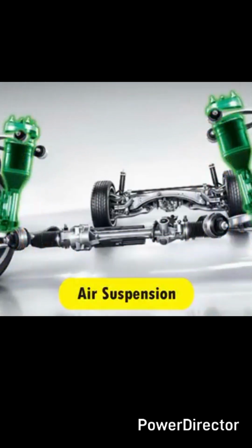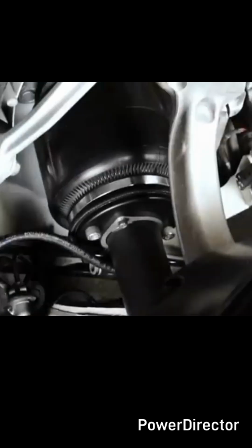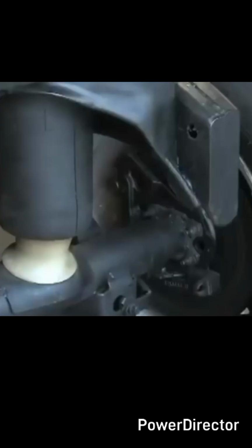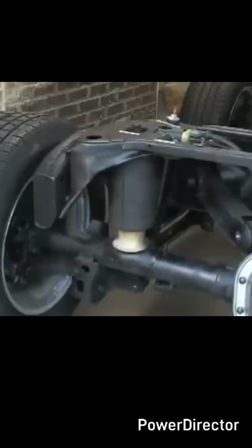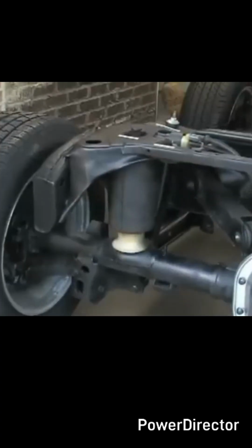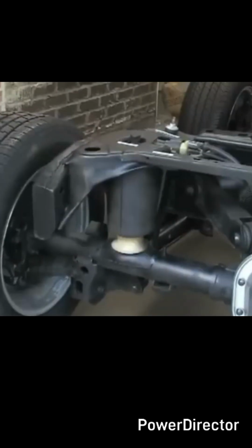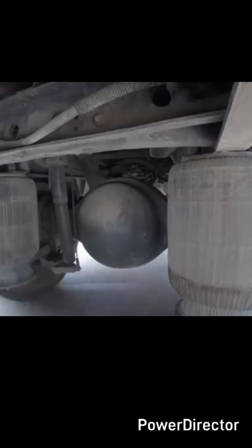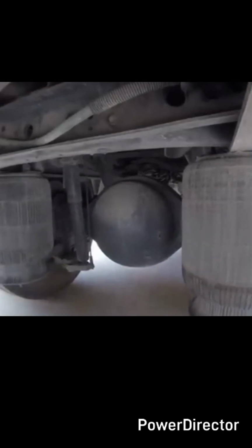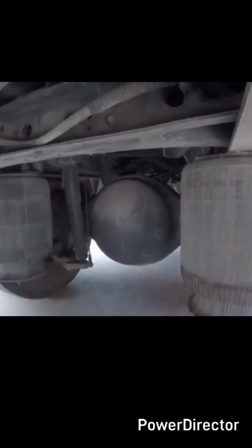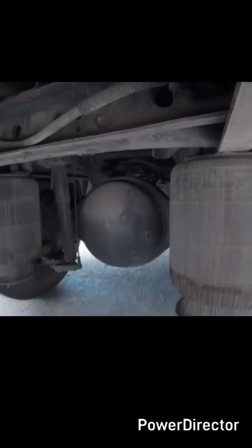In air suspension system, an air spring is used instead of a mechanical spring. Air spring has a higher load carrying capacity than a mechanical spring. Air spring also has the advantage of variable spring rate by adjusting air pressure, which is not possible in the case of a mechanical spring. In air spring, two ends are provided. One is mounted on the frame, and the other to the swing arm. Three connection lines, which are pressure line, return line, and control line, are also provided for the operation and control.